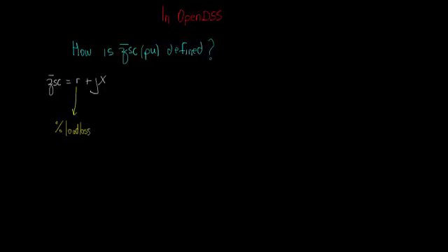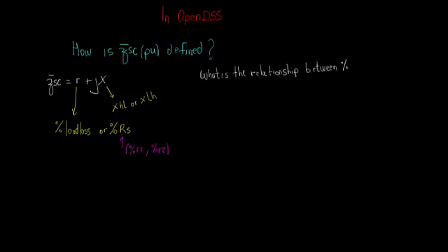Let's start with the short circuit impedance. It can be written as a resistance plus a reactance. In OpenDSS, the resistance can be specified by using either the parameter %loadloss or %Rs, which contains the pair %R1, %R2, the per unit resistance of each winding, whereas the reactance can be specified through the parameter XHL or XLH for a two-winding transformer.